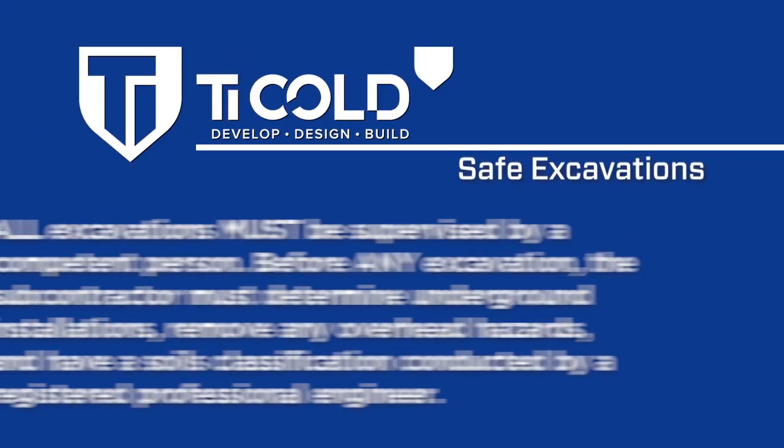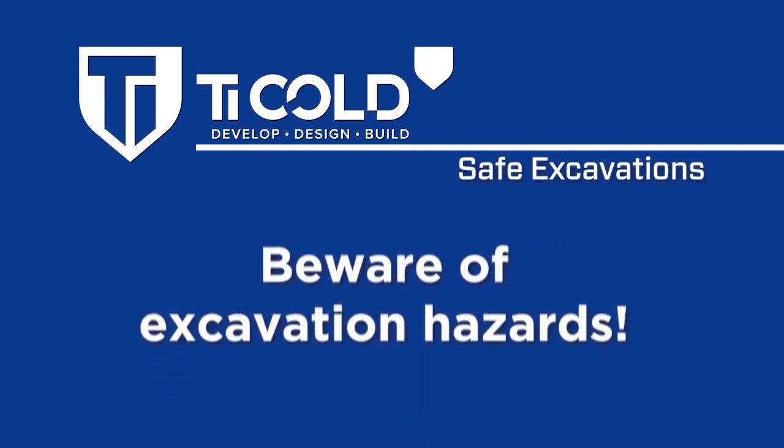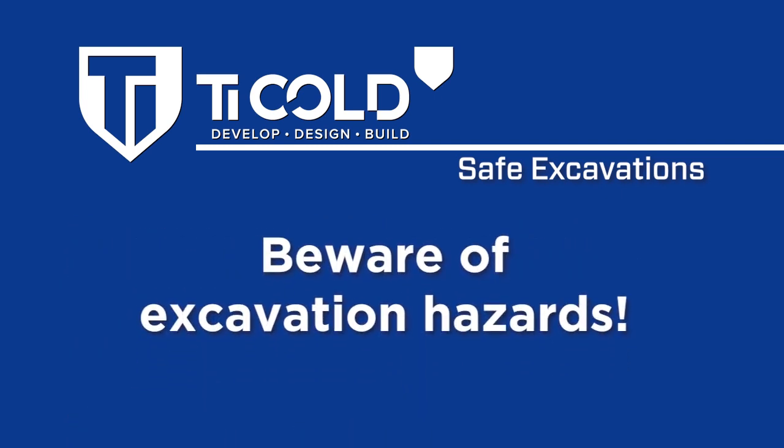Safe excavations. All excavations must be supervised by a competent person. Before any excavation, the subcontractor must determine underground installations, remove any overhead hazards, and have a soils classification conducted by a registered professional engineer. Beware of excavation hazards.